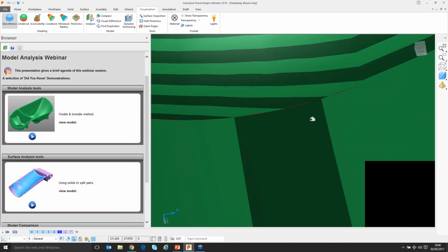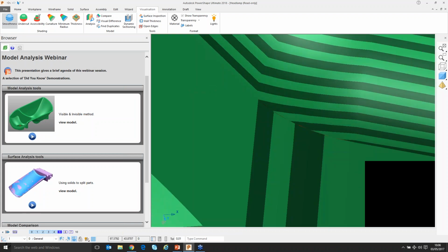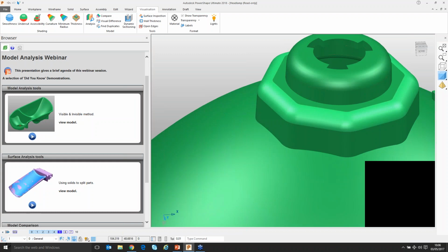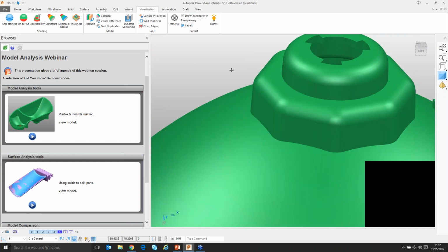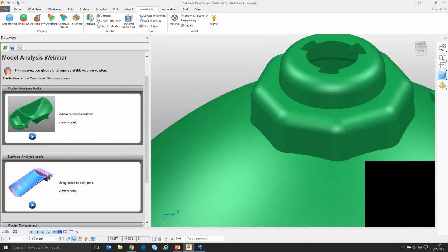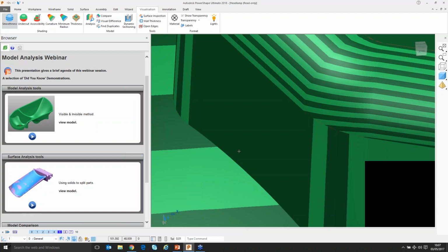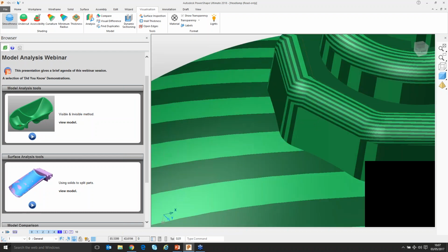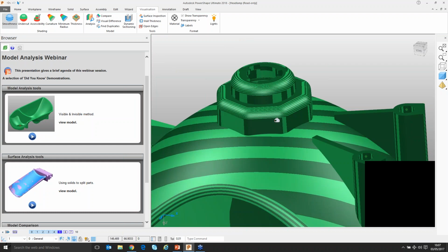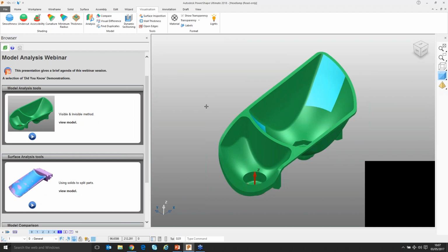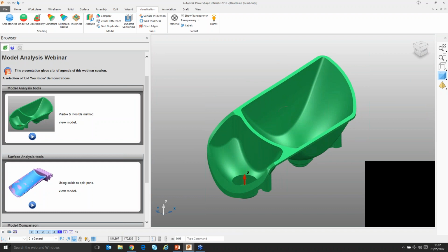Now I thought that was tangential down there, and without this tool it would not have been particularly easy for me to detect that they were not. Can you see there? That all looks good to me by eye. It's only when I isophoto or smoothness shade that I see that there are issues in that region. And of course I can then go on to use PowerShape to fix those easily. Okay, so that is the smoothness or isophoto shading. Let's undo that color change operation and move on to look at something else.